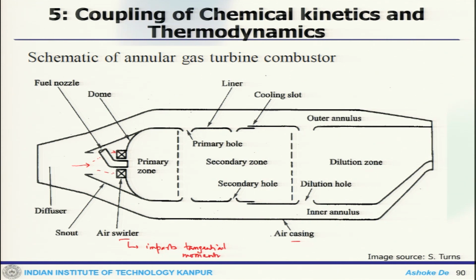to the air. Essentially, when you put so much energy into it, the flow becomes purely three dimensional. This does a lot of things. It not only allows rapid, quick mixing, it also makes the system more turbulent in nature. So, there is a very specific purpose of using this kind of swirler, and then the fuel comes in, so that gets well mixed. If it is a liquid fuel, then that will atomize and evaporate, and then the air